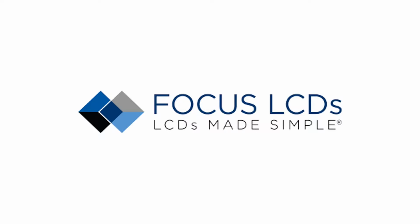Today we will show how to dim the LED backlight of a character 16x4 character LCD using PWM, or pulse width modulation. PWM is a digital signal limited to only two levels. It's either on or off. By varying the proportion of the on time compared to the off time, the width of the pulse is so modulated. Modulation is a simple yet effective control method to control devices or circuits, one of which is the dimming